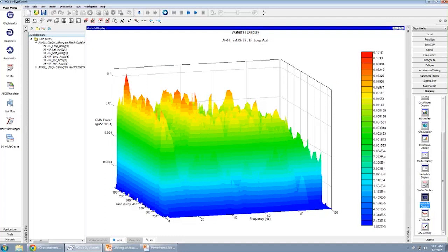or we could instead do a peak hold where instead of getting the average of all these peaks, we might just be grabbing this one particular one, and that would be something that occurred maybe 100 seconds in, representing a worst case peak at maybe about 5 Hertz. So there's yet another way that we can look at our time series data in the frequency domain three-dimensionally.